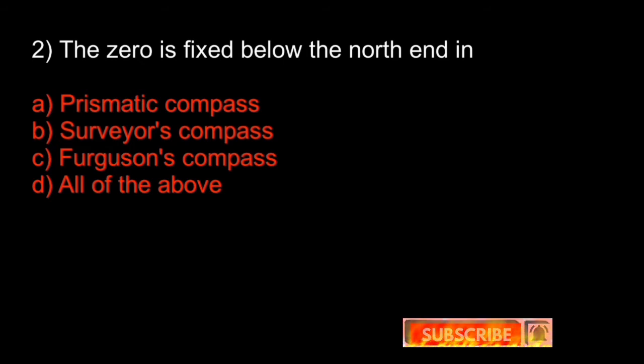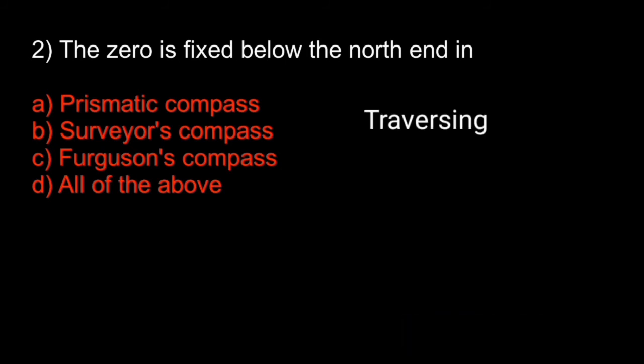And compass surveying is not used in places which contain iron ore, power lines, etc., which usually attract magnets due to their natural properties and electromagnetic properties respectively. Compass surveying is done by using traversing. A traverse is formed by connecting the points in the plot by means of a series of straight lines.